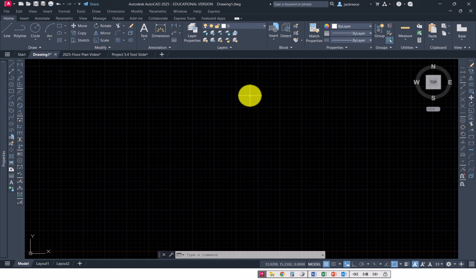I teach my other AutoCAD classes to create a layer called construction, and then you draw all of your construction lines on that layer. The reason is that when we get to creating blocks, think of a block as a catalog item for something that's used quite often, like a door or a toilet fixture or a bolt or a spring.